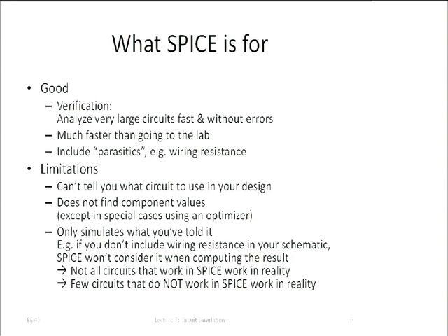But there are very, very few circuits that do not work in SPICE, but then in reality actually do work. I mean, there are special cases where that could happen, but it's very, very rare. So most of the time, in general, we are much better off figuring out, this is sort of, we have a necessary but not sufficient condition, to use a mathematical term. If we use SPICE to pass the first check, we still have to build the stuff to make sure that it's actually working.